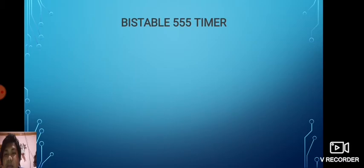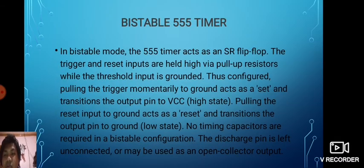Bistable 555 timer. In bistable mode, the 555 timer acts as an RS flip-flop. The trigger and reset inputs are held high via pull-up resistors, while the threshold input is grounded. This configuration means pulling the trigger momentarily to ground acts as a set and transitions the output pin to VCC, the high state.